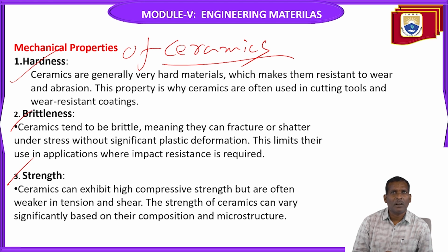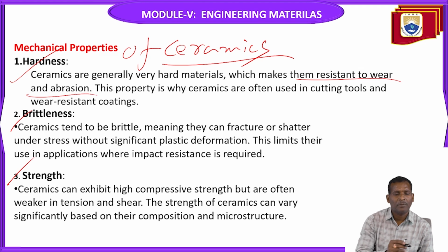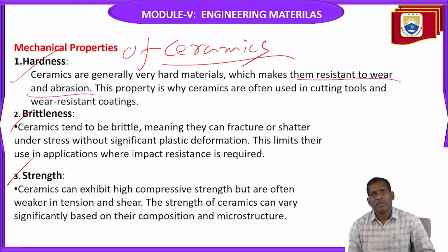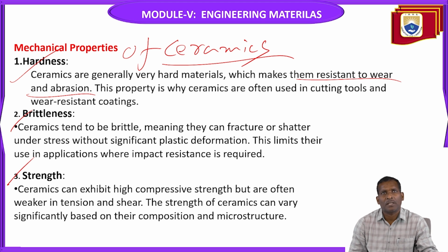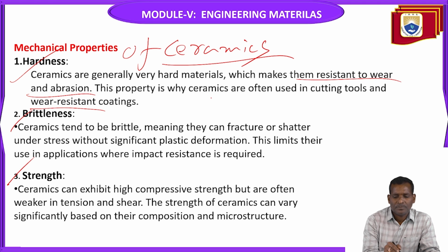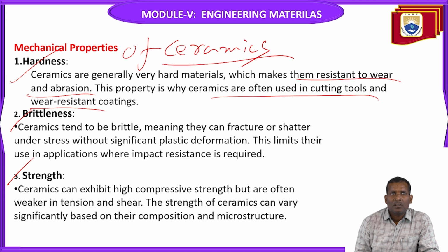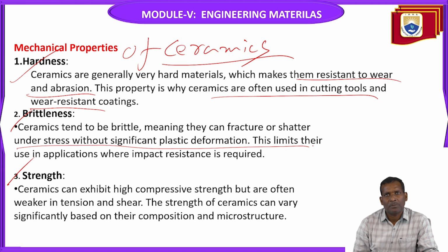Ceramics are generally very hard materials, which makes them resistant to wear and abrasion. These properties mean ceramics are often used in cutting tools and wear-resistant coatings. Brittleness: ceramics tend to be brittle, meaning they can fracture or shatter under stress without significant plastic deformation. This limits their use in applications where impact resistance is required.